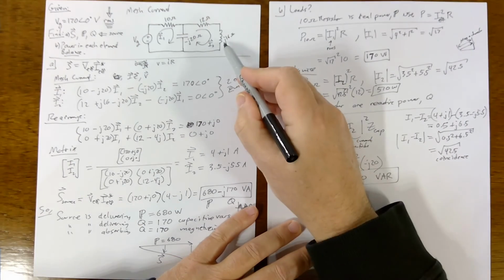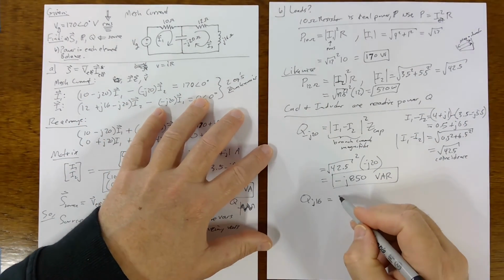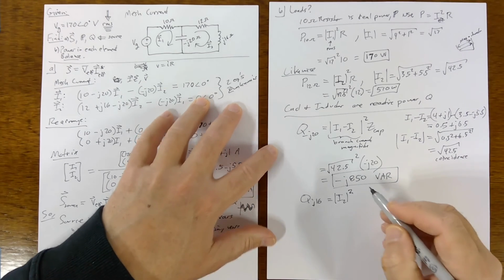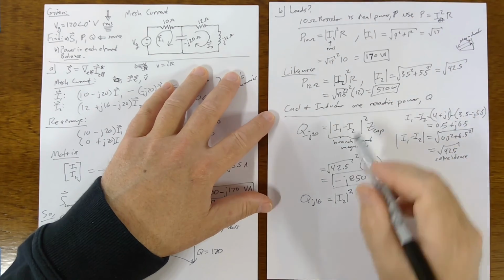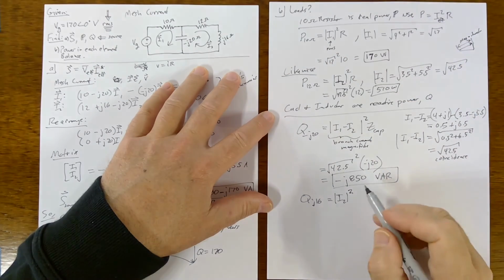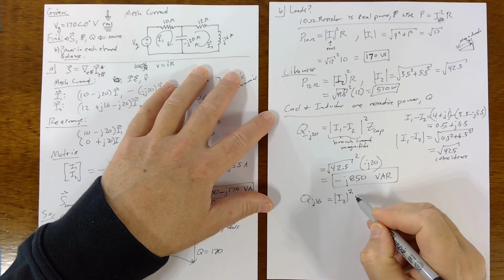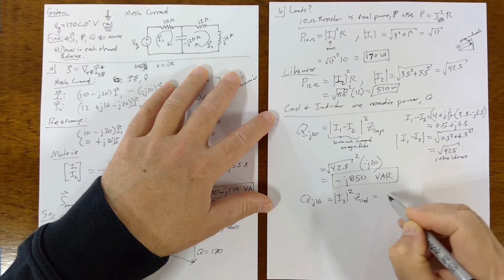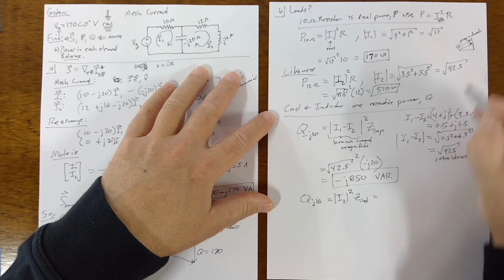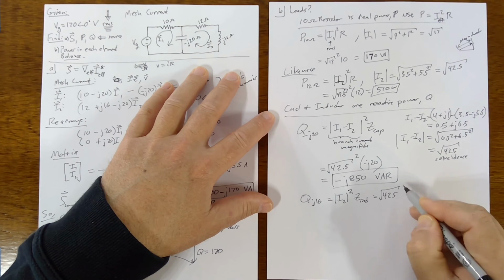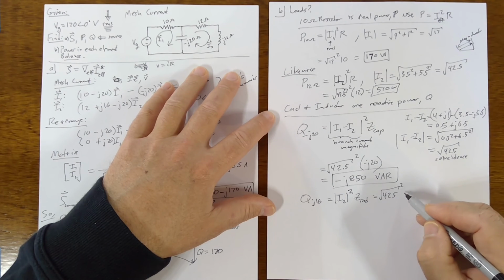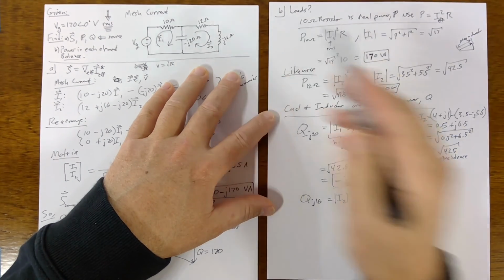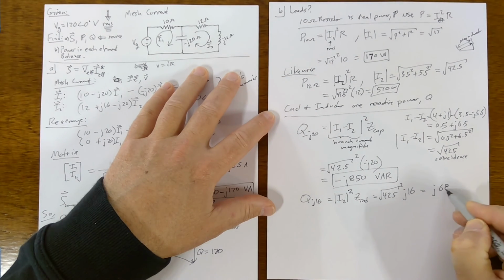This is going to be the current through it, which is I2 that's going through there. We want the magnitude of that squared. You realize we're just using I squared R sort of, but with little variations to account for the fact that it's phasors times the impedance of the inductor. We already calculated this, it's over here. So it's root 42.5, quantity squared, times J16, the impedance of the inductor. So it works out to J680 VAR.